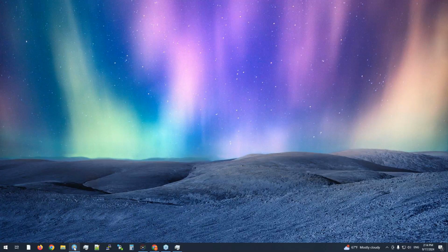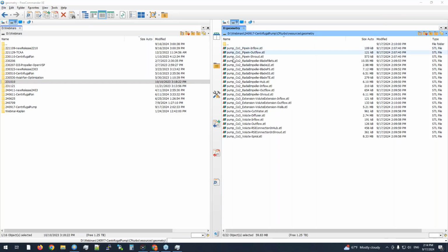So what you need to have at the beginning is the set of STLs which fully describes your flow domain. It needs to have several properties which we have already talked about. It needs to cover the basic patch categories: you need to have the inlet patch, the outlet patch, and you need to divide the walls of the rotating parts and non-rotating parts. So it needs to have some kind of intuitive splitting of the boundaries of your flow domain to be able to properly describe boundary conditions and interface conditions on the neighboring components, rotating and non-rotating parts, etc.